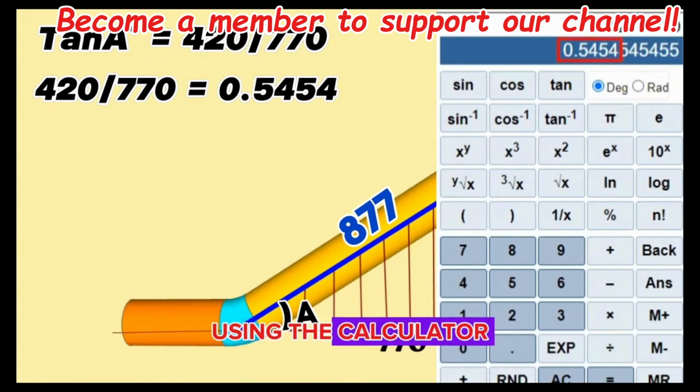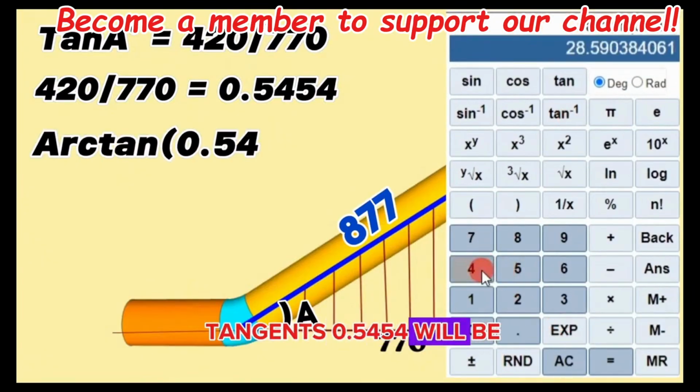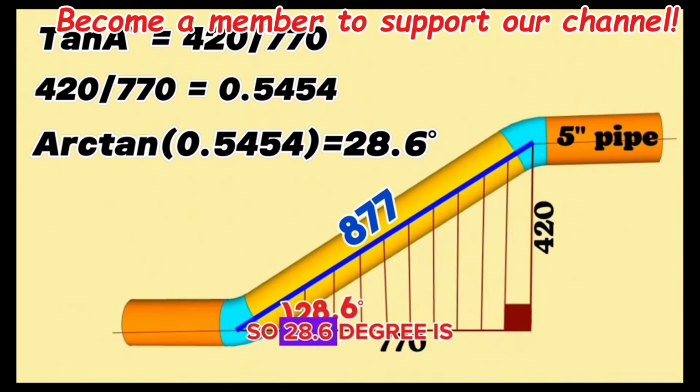Using the calculator we find that arctangent 0.5454 will be equal to 28.6 degrees. So we calculated and found that the cutting angle of the following elbow is 28.6 degrees. 28.6 degrees is one of the acute angles of the right angle triangle.